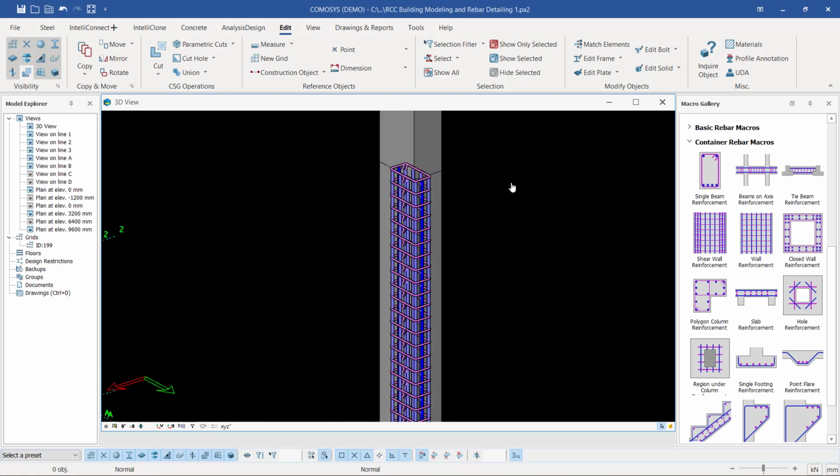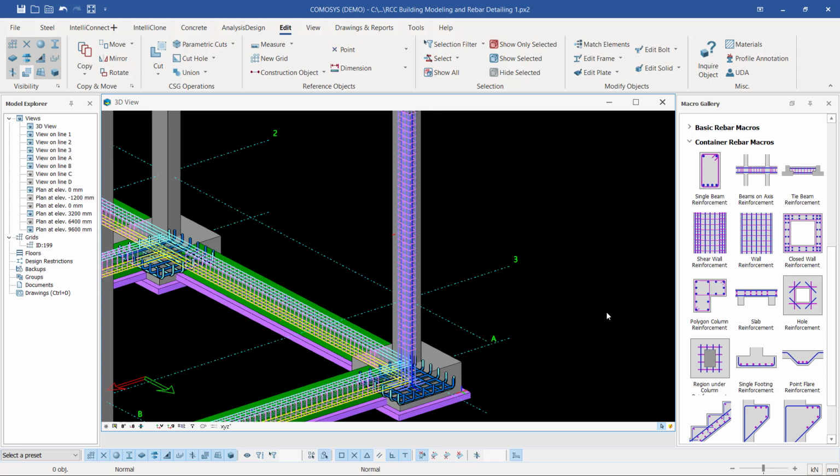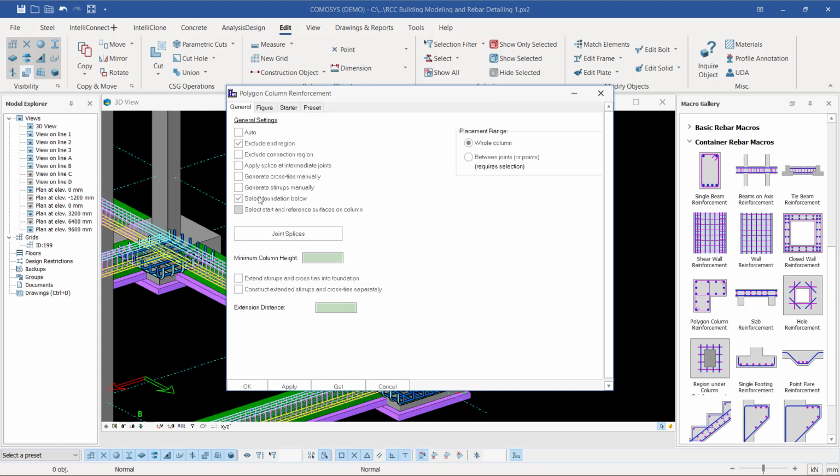And I think you're wondering why I'm following the process. I select, then right click, then I select the base plate. Those rules are defined here. Let me right click here and you can see the rules. There's an auto option, and you follow the checked rules.